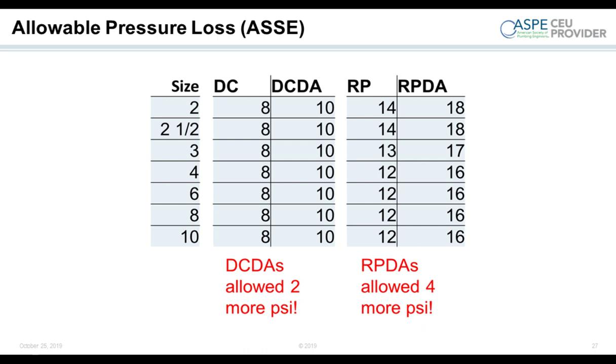In fire applications, an engineer needs to prove, through hydraulic calculations, that the very furthest sprinkler head will get adequate flow if there's a fire. So a couple PSI could mean the difference between sizing a riser up or adding a booster pump, which is a lot of money to the customer.